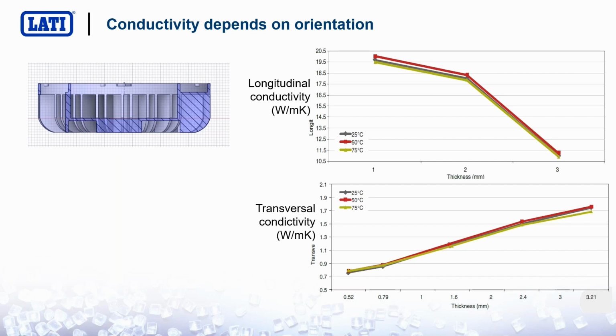And in some cases, you may need the transversal conductivity to be higher. So depending on the situation, and typically you want heat to be transferred efficiently from the heating source to the surface, so to the fins, so in the transversal direction. A higher base thickness helps increase the average thermal conductivity in order to exploit the best of this material. Sorry, I forgot to tell, this is of course related to anisotropic fillers such as graphite.